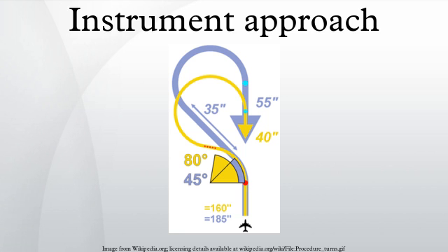A zone between the runways is designated as the no transgression zone, and if either of the aircraft nears or strays into this zone, the other approaching aircraft is told to break off by the PRM controller, at which point that aircraft must veer away from the approach path. The aircraft must have 2 radios, one tuned to the tower controller in the usual way, and another tuned to the PRM controller.